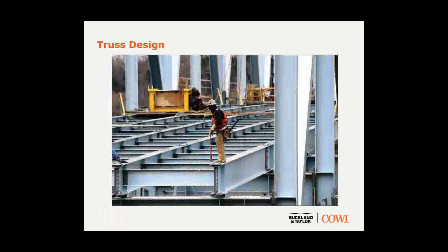The floor system is continuous end to end of the bridge, so roughly 2,430 feet long, with no joints in the deck, and expansion joints only at the two ends of the bridge. So this means that the entire steel floor system had to float over top of the floor beams on bearings. So there's multiple bearings every time a stringer crosses a floor beam, and anchored only at the very middle of the bridge over the center pier.